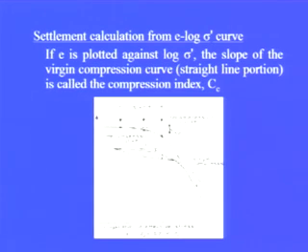Now in this particular case we can see, if we have the load, the void ratio and sigma bar curve for a particular soil, then this particular soil has already experienced a load corresponding to this particular stress.